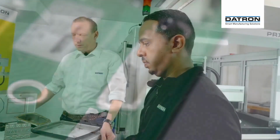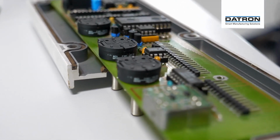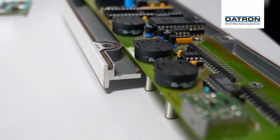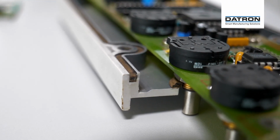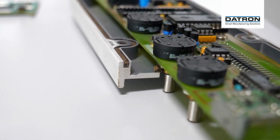Okay, I guess that's all. Did we talk about the combi dispensing? Yes, here we have a combi dispensing. This is a DATRON specialty, where we have the EMI material and silicone together. The core of the EMI gasket is silicone, and the EMI material is outside, as the cover. And this cover is the functional part, the EMI shielding part, and what is happening inside doesn't matter.